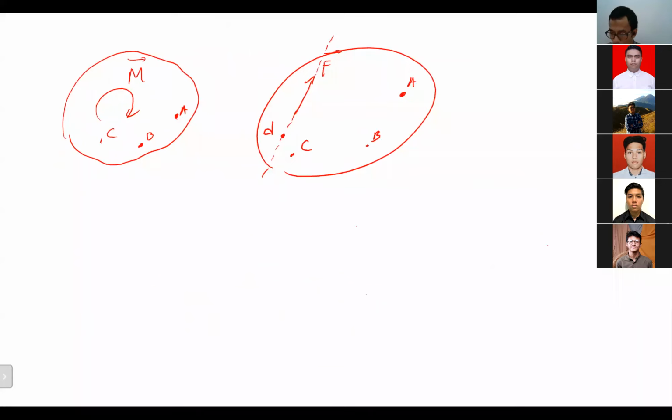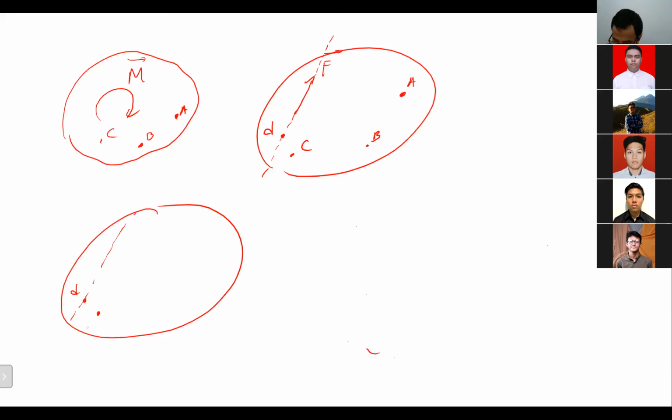So for example, if I want to move force F to point C, this is the new body. This is D. Previously, this is our line of action. Now I move it to point C. This is the new line of action, still in the same direction but parallel to it. And the perpendicular distance is this one. We normally call this perpendicular distance D. Then this is C.